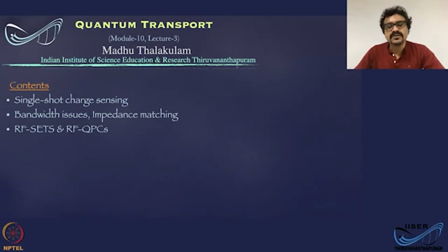In the previous two lectures, we discussed single charge sensing in quantum dots using two kinds of charge detectors or charge amplifiers. One is the single electron transistor and the other one using quantum point contacts. So in this lecture, we will discuss single shot charge sensing.